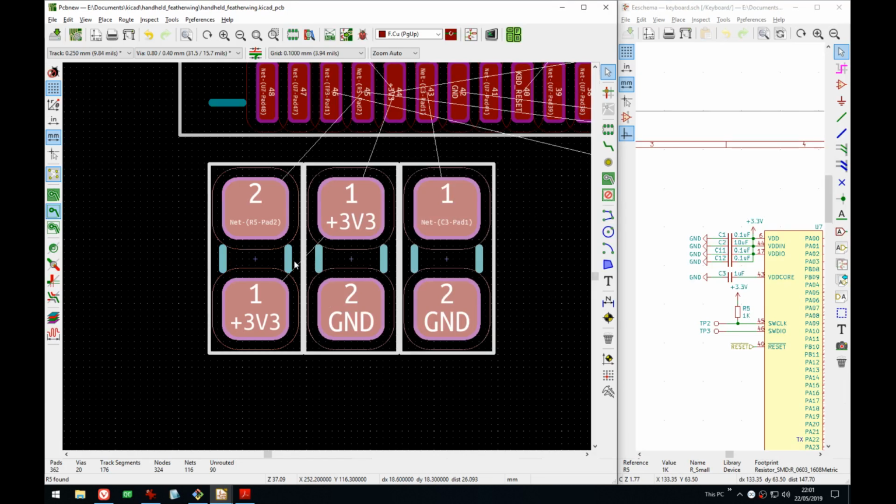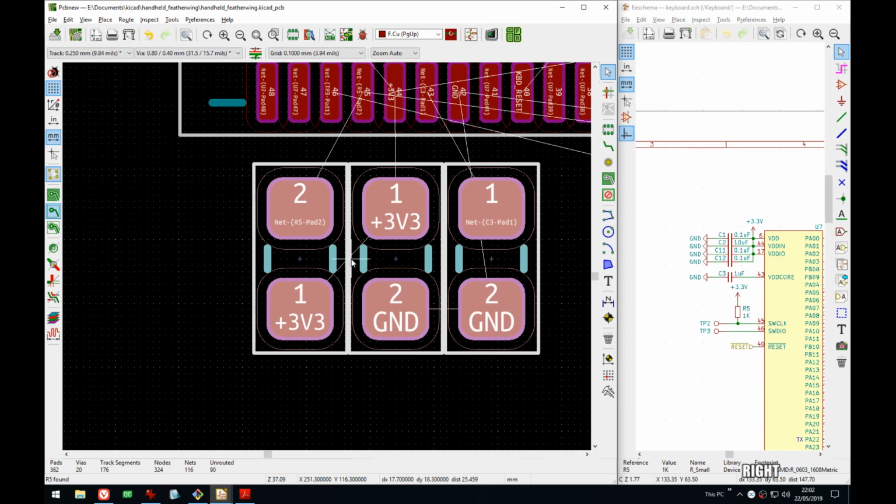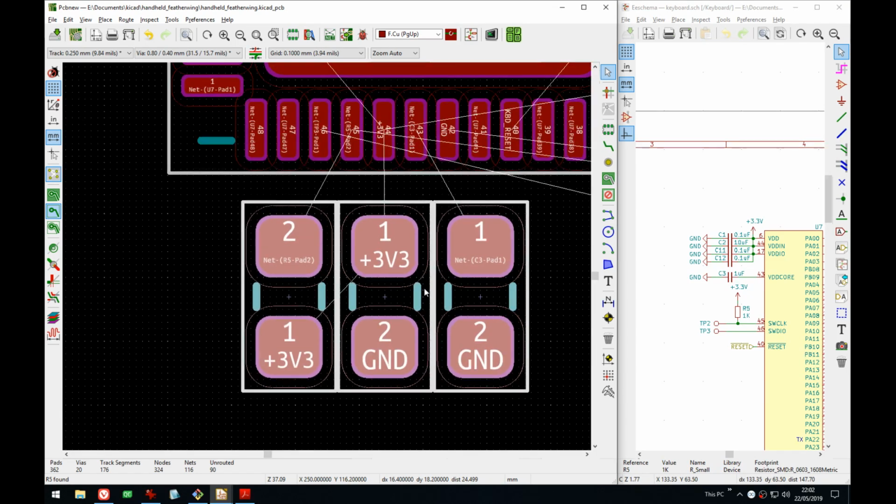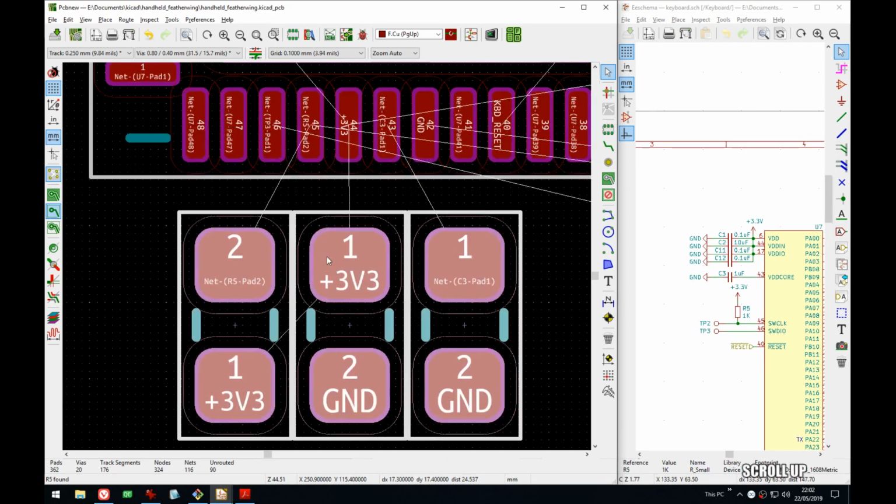So you can see here my courtyards right now, they are touching, but I have tested it with 0603, and with 0603 this is good enough. Or 0402 starts getting really close, and it's actually hard to place them because if you're between two, the tweezer actually can't fit anymore.